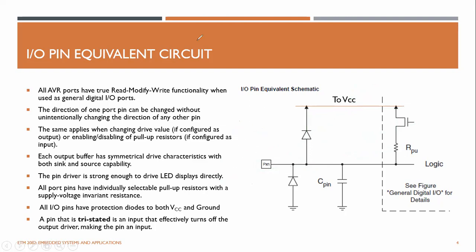And also, like I mentioned, sometimes you have 5 volt, sometimes you have 0 volt, like this is digital. Assuming this is a 5 volt microcontroller, this should be 0 volt, but due to some surges, this could also have some bumps, right? Now this voltage could go down to a negative voltage, like -1, right? Due to some kind of inductive switching or something. So it should be nice and clean 0 volt, but we can't predict. Due to some sort of external effect, the voltage could drop to -1.